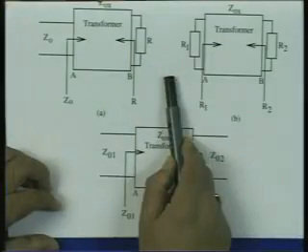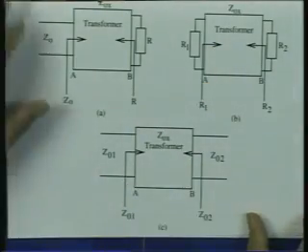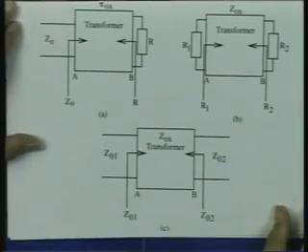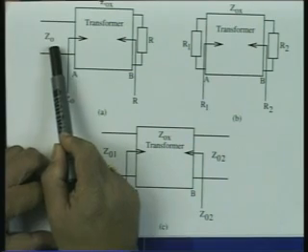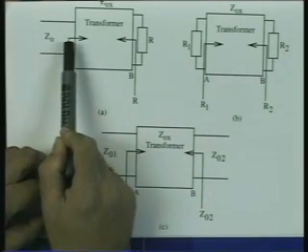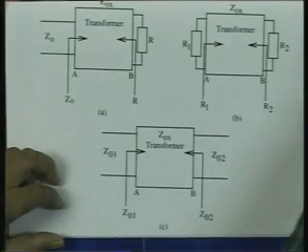So, matching a resistive impedance to the characteristic impedance has many practical applications. Let us see how we do that now. Firstly, we will note that if you have a resistive impedance and it has to be matched to the resistive impedance, the impedance seen from the left side should be the resistance. Let us go to our Smith chart and ask: if I have an impedance which is a resistance, then how much should I go on a transmission line so that the impedance always appears like resistance?